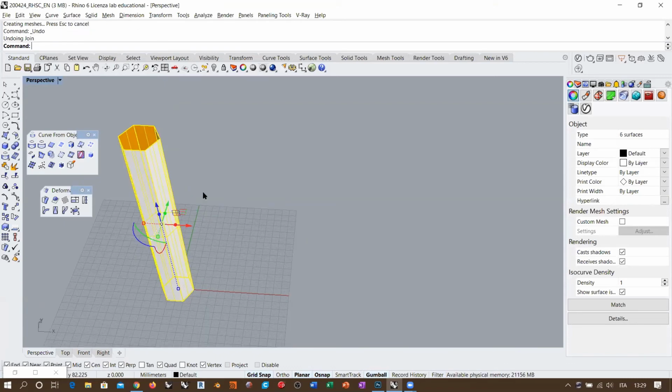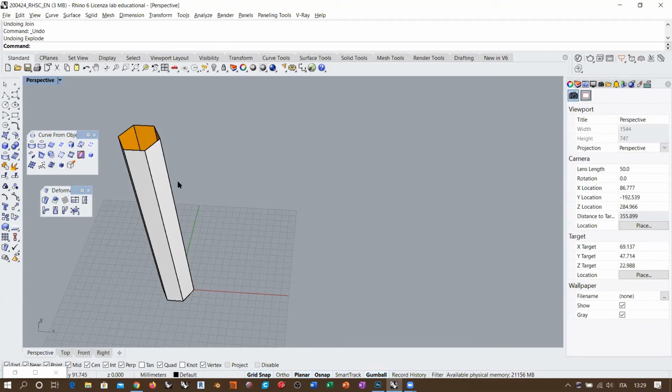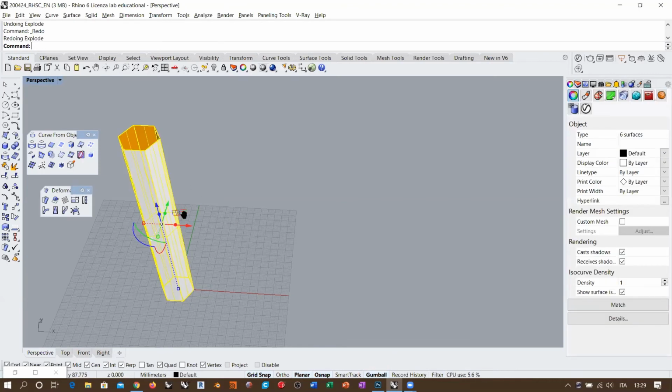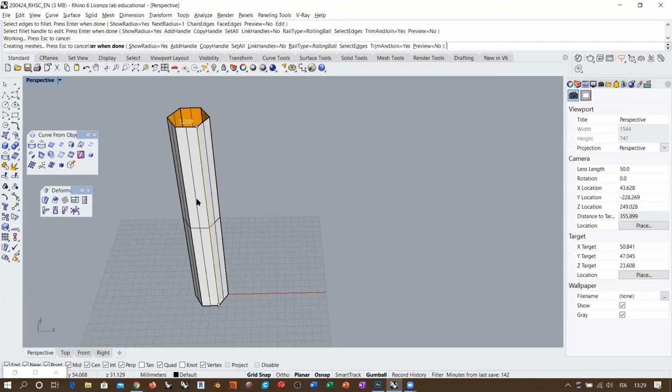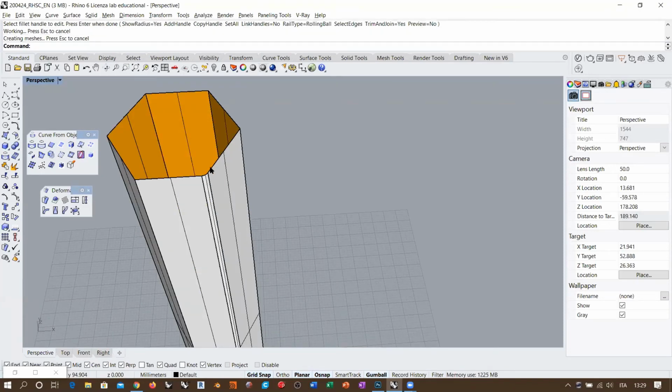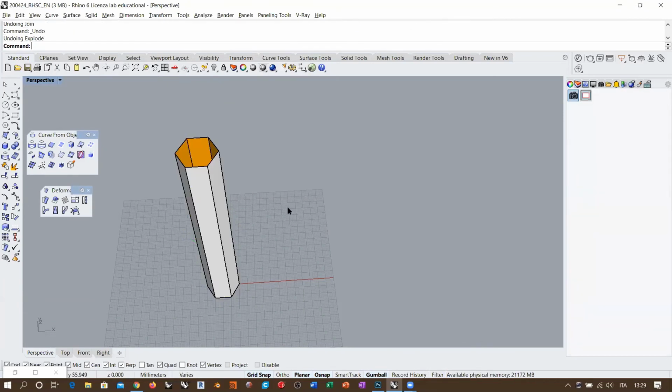Okay? But what I can do eventually is one thing, and you already know that this is not the proper solution, I could fillet all the edges, but I will create two discontinuities instead of one single discontinuity, okay? Because there is a change of curvature. And so in this case, it will result in filleting the edges with a radius of 1, for example. If I fillet this, I get this, two discontinuities instead of one. Okay, so I am increasing the amount of complexity.